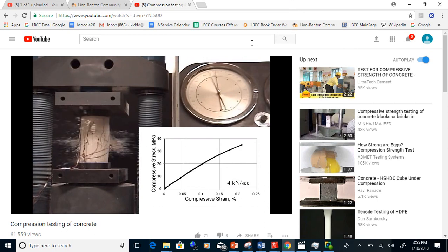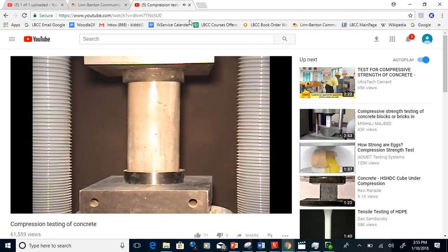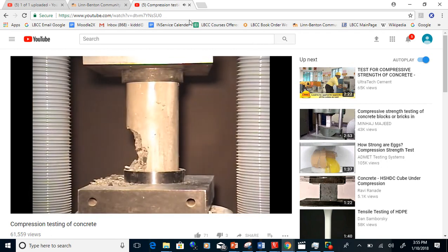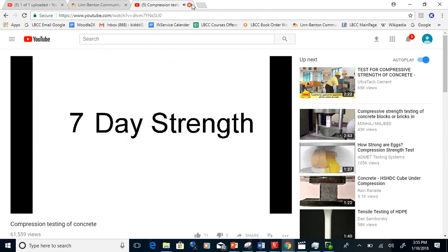They add rebar to make it more ductile. When they add rebar to concrete columns like that, does it make it more ductile? Well, the steel is more ductile. It doesn't make the concrete more ductile, but it gives a framework for everything to hang on to. It also gives it tensile strength, so it does a few things. Concrete has to cure. 28 days is the standard for getting full strength or close to full strength.